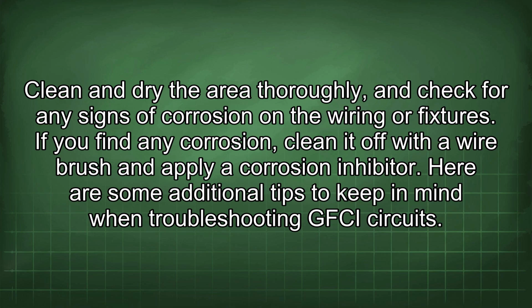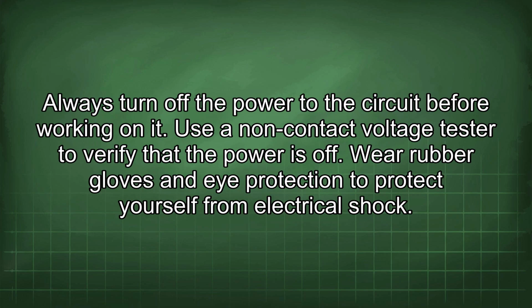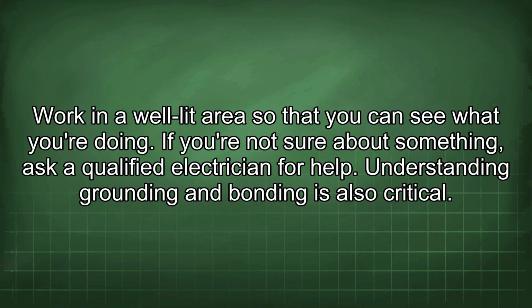Here are some additional tips to keep in mind when troubleshooting GFCI circuits. Always turn off the power to the circuit before working on it. Use a non-contact voltage tester to verify that the power is off. Wear rubber gloves and eye protection to protect yourself from electrical shock. Work in a well-lit area so that you can see what you're doing. If you're not sure about something, ask a qualified electrician for help.